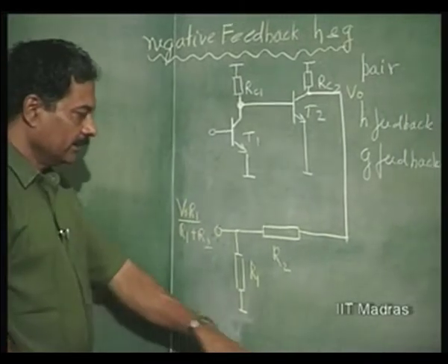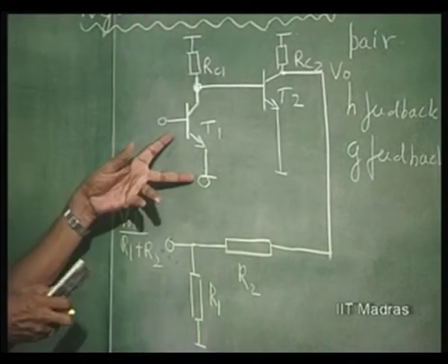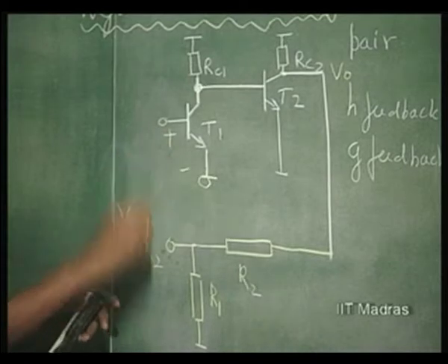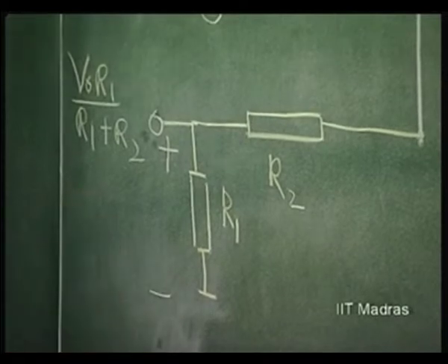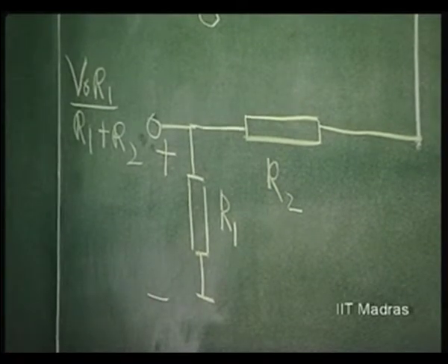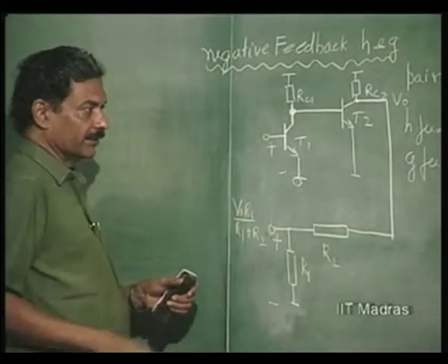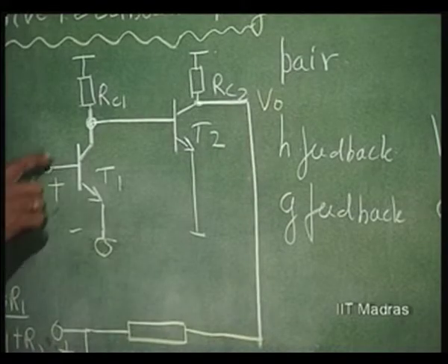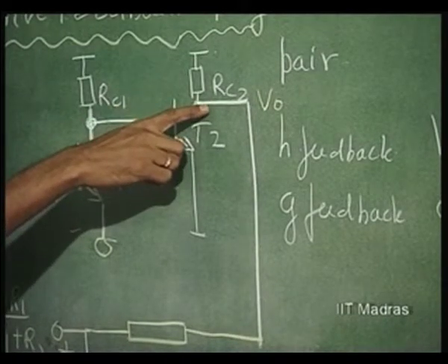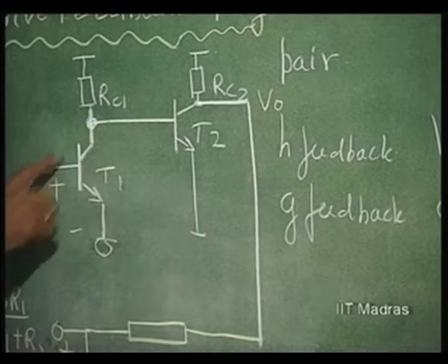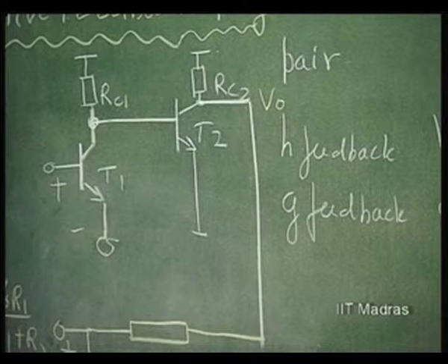that is going to be put in series with the original input. The original input of the amplifier is this, right. This is the feedback voltage. So, we are going to lift this and put it in series. From here to here the phase shift is 180 degrees, from here to here again the phase shift is 180 degrees, and therefore, from here to here the output and input voltages are in phase.